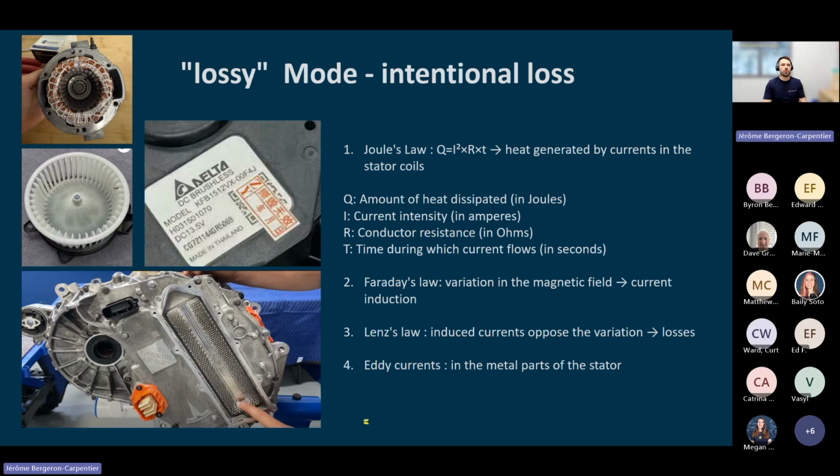So running coolant to the heat exchanger for those motors, it's going to be able to capture a lot of energy, a lot of heat. So that's one strategy that is super useful when it's super cold outside and the refrigerant is not able to capture any more heat from the outside because it's too cold outside, right? So then the car can generate its own heat. But I mean, you won't lose that heat because it's going to be transferred to whatever it needs to.